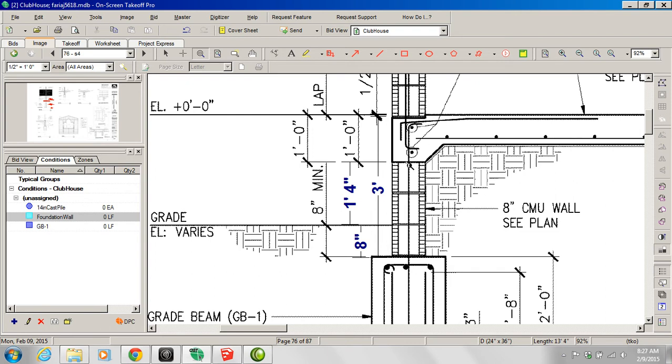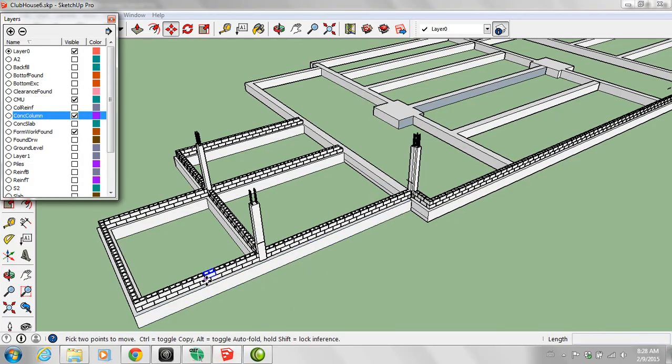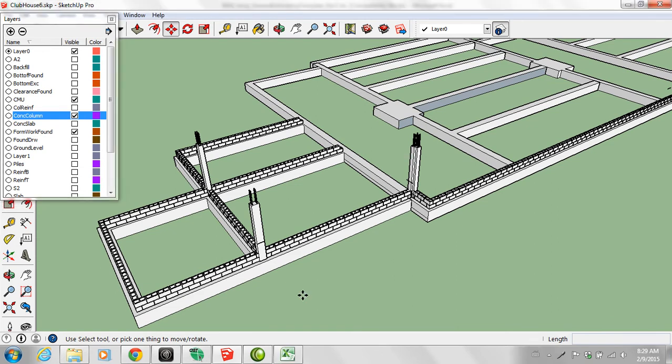So we can safely say that from the bottom of the base for the slab to the top of the foundation is going to be 2 feet. So that's going to be the height of our foundation wall. We are going to consider that the entire foundation wall is 2 feet high, and it runs on top of the entire foundation.